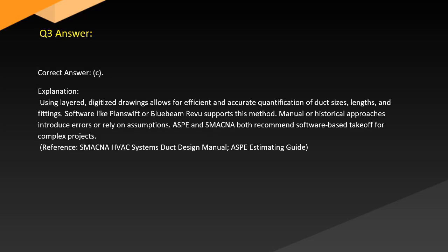Answer. Correct answer: C. Explanation. Using layered digitized drawings allows for efficient and accurate quantification of duct sizes, lengths, and fittings. Software like PlanSwift or Bluebeam Review supports this method. Manual or historical approaches introduce errors or rely on assumptions. ASHRAE and SMACNA both recommend software-based takeoff for complex projects. Reference: SMACNA HVAC Systems Duct Design Manual, the ASPE Estimating Guide.